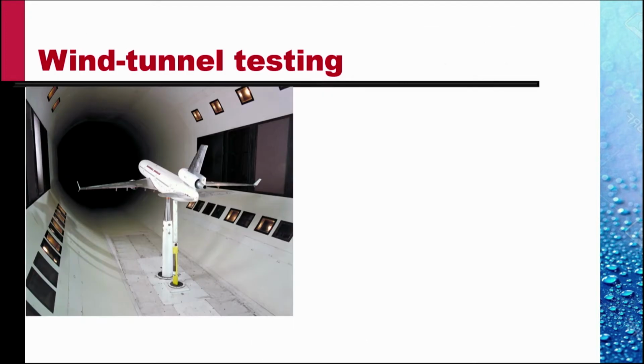Let's revisit the wind tunnel testing of aircrafts and aircraft components. The air blows at large speeds in a tunnel. The aircraft or aircraft model is kept within the tunnel, and forces that the air applies on this model are measured, and from this, prediction of the forces on the full-scale aircraft are obtained. The forces of interest are the inertial, viscous, and compressibility forces in the air.